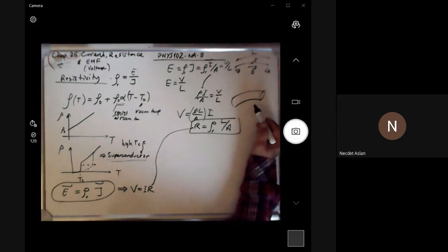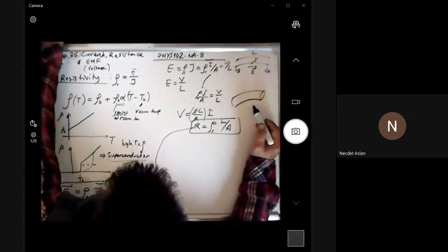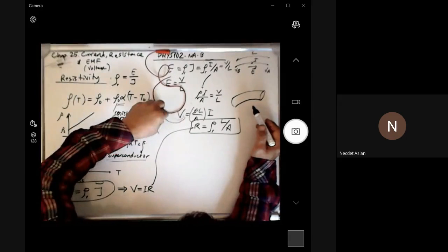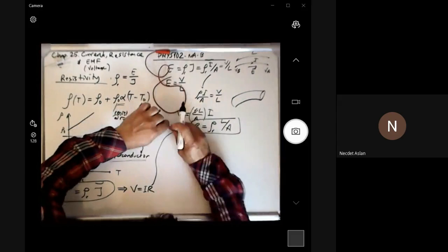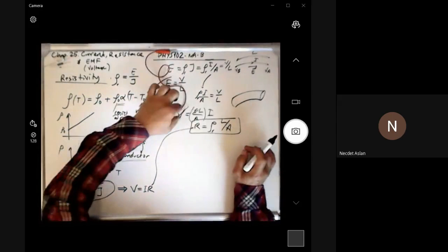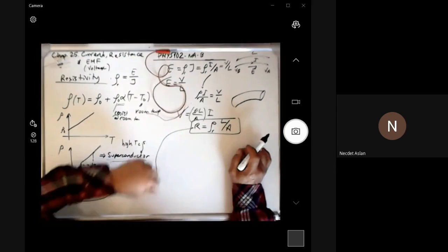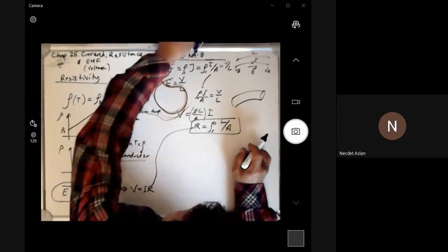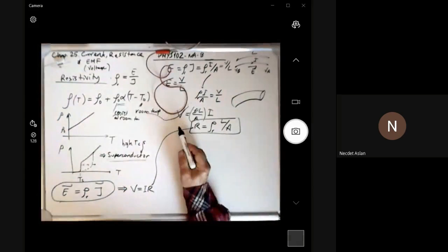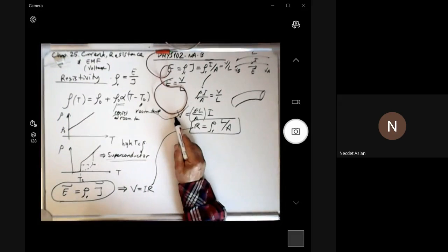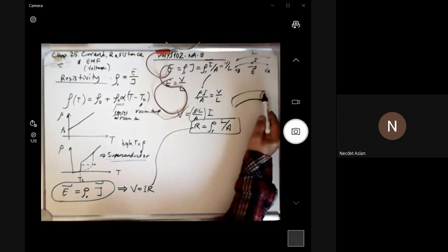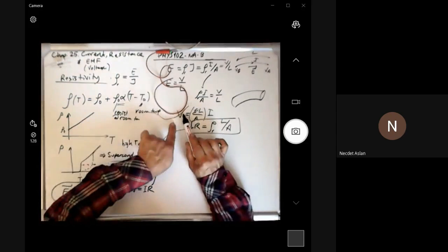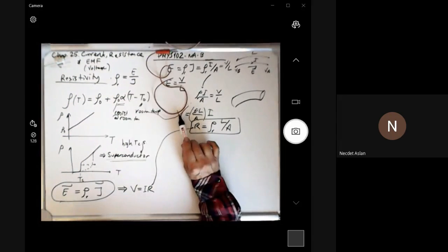Now, which one of these cables do you think has greater resistance? This is one cable and this is another cable. This cable is thicker, but this cable is thinner. I have another wire which has even greater thickness like that. If we cut the same lengths from these wires, this one will have more resistance. Why? Because the cross-section area is smaller. The lengths are the same, but the cross-section area is smaller, so this will be more resistive. The small one is more resistive to current.